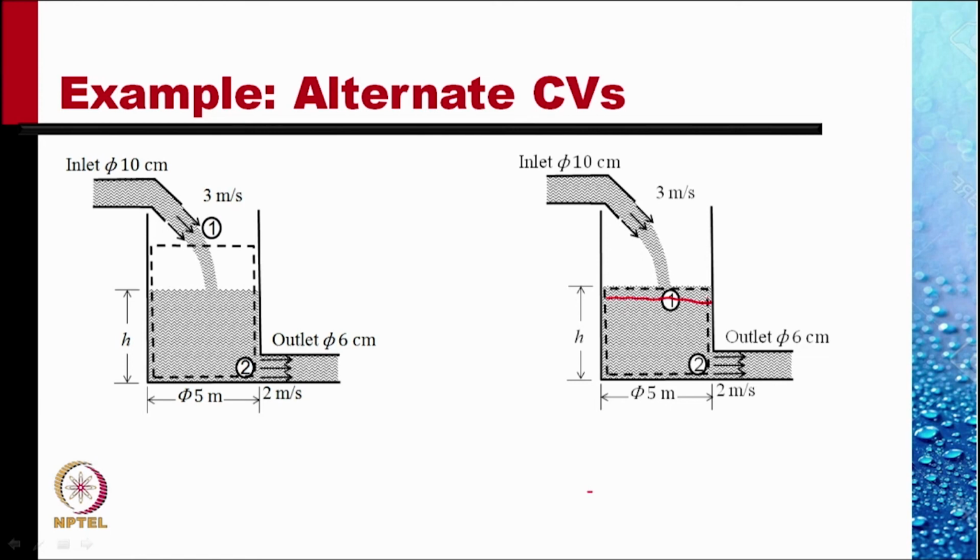Yes, we can apply. But we must realize that while calculating the influx and efflux, we must take the velocity of the fluid relative to the control surface. Here, the control surface is moving up at the rate dH by dt. And so the average velocity of influx at that surface would be velocity of water plus dH by dt.